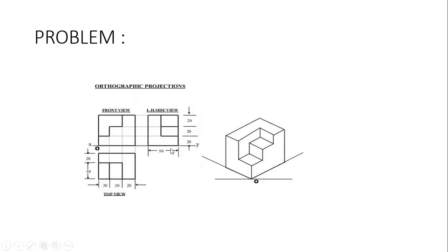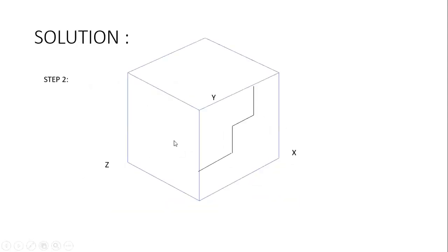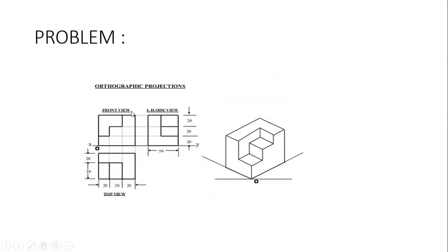The side view measures the width and the height of the object. So it is mandatory to start drawing from the front view's direction, because the front view gives the true, real original shape of the object in 2D.